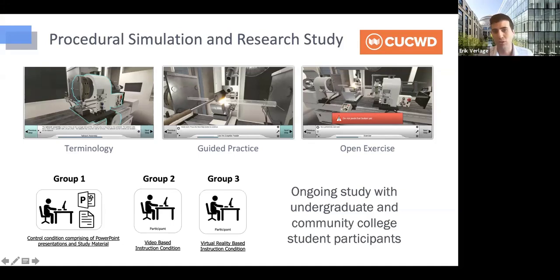simulation to train students in how to operate a lathe for fiber manufacturing. So what they're doing here is they're taking a tube of glass, depositing materials on the inside of it to create a higher index material, then collapsing the tube that will then become a rod of glass that will then be drawn into optical fiber. So in the end, after you draw it down, you end up with very thin strands with a very thin inner core that is a little denser, higher index material, and then the outer cladding, which is the original glass from the tube, and that's the optical fiber. So that's how you create optical fiber.